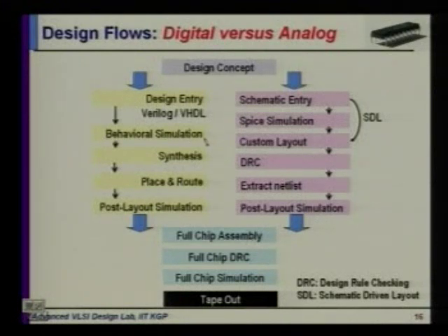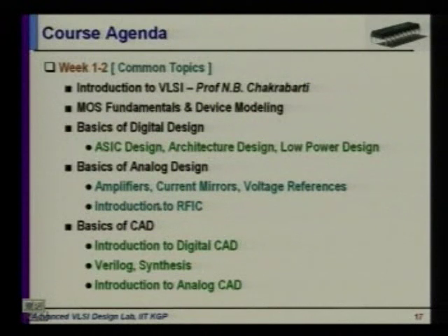There are some intermediate hooks here which I have not shown, where you can actually do a behavioral simulation and a SPICE simulation of the analog together. So there are new kinds of platforms where you can have the analog part at the transistor level, you can have the digital part in Verilog or VHDL, and you can simulate them together on a mixed mode simulator. Okay, so that helps you in doing a lot of verification earlier in the design flow, and then the analog flow takes this part and the digital design flow takes this part. Okay, this is the agenda of the course.